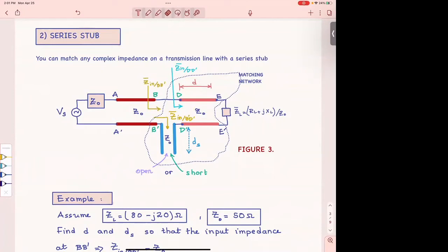If you have a load like this, which is 80 R sub L minus j20, means it's capacitive, it has a resistor in series with a capacitor as your load, according to what I see here. Then you will need to, one way, if they allow you to use lumped elements, will be to put an inductor here, to cancel the capacitor, cancel this, minus j20.